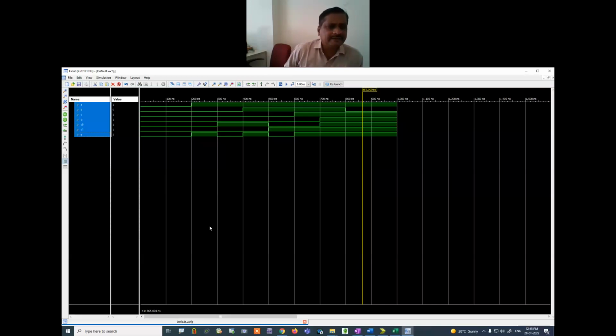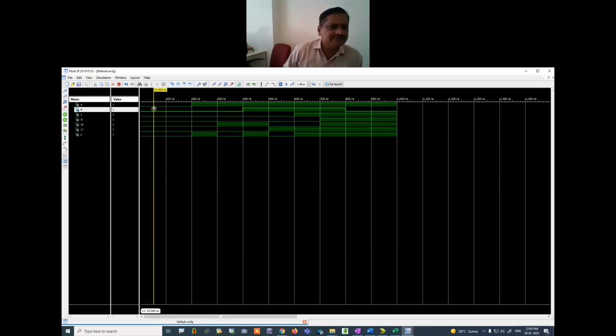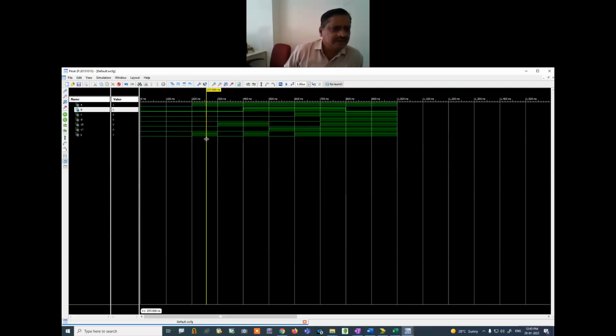Now look at here. In this portion everything is 0 0 0 0 0. Now we can test here. Now look at the S0 and S1. What is this? This is 0 and this is 0 at this point. At 0 0 0 0, what output should come? What should be the output? Output should be same as A. Now look at what is my A. My A is 1, that's why output is 1.